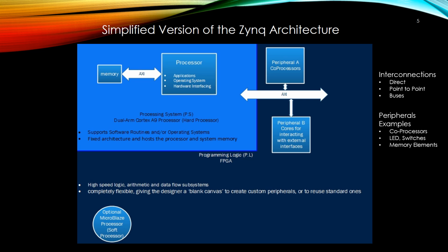It is important to know that the Zynq is an SoC, which means a wide variety of standard intellectual property, also known as IP, is available. This means that there is no need to redesign these components. The PS and PL can be used independently or together, and in fact, the power circuitry is configured with separate domains enabling either the PS or PL to be powered down if not in use.